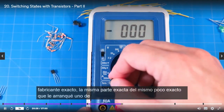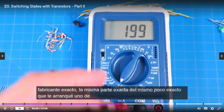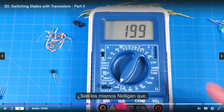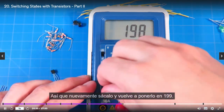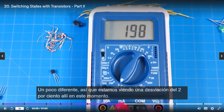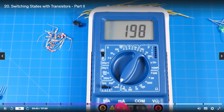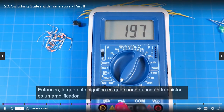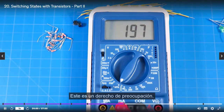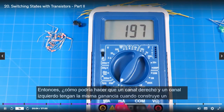Now the same exact manufacturer, same exact part, I ripped them off one of these. Are they the same? Now look at that. Again, take it out, put it back in. 199, so a little bit different. We're seeing about a 2% deviation there. What this means is, when you use a transistor as an amplifier, this is a concern. The gain is potentially different for every transistor. So how on earth could you make a right channel and a left channel have the same gain?